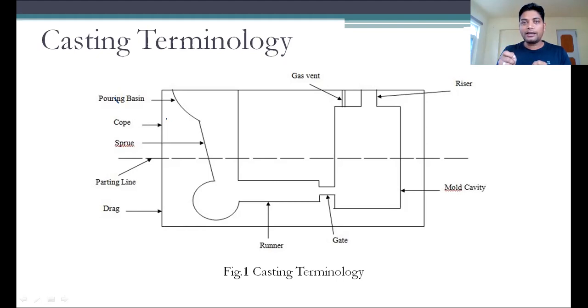It's not like water filling the bucket, where the bottom part is still water. When the molten material is first poured into the bucket, the bottom part becomes completely solidified. So this is a very high rate of cooling, or contraction. Here we are using this pouring basin. Now this pouring basin we keep sometimes in this shape, or exactly if you see, it will be in this shape. Sorry.